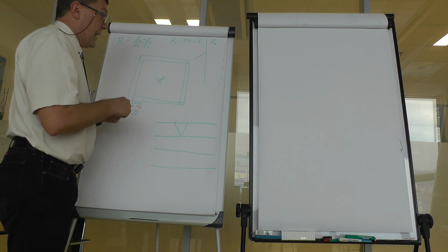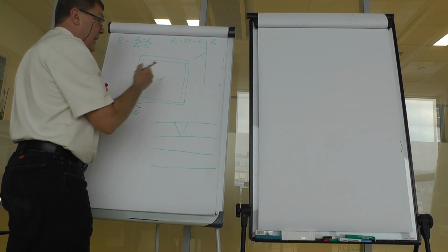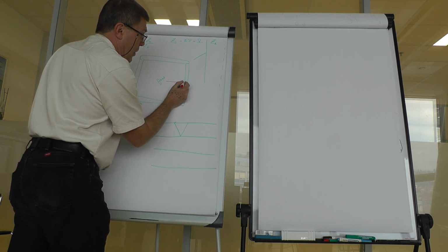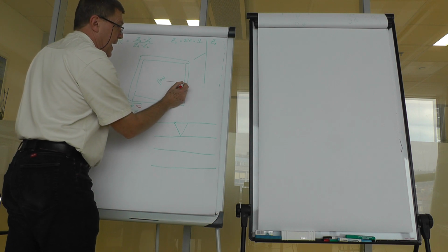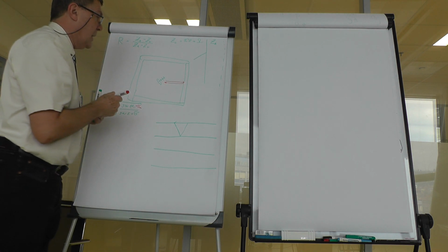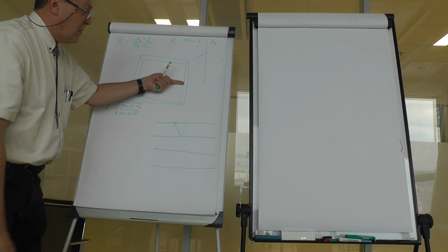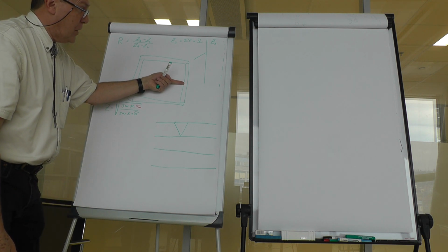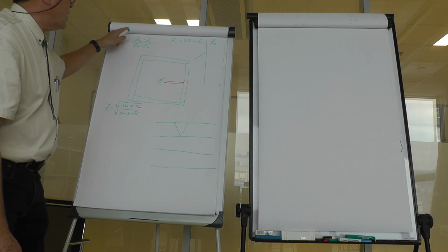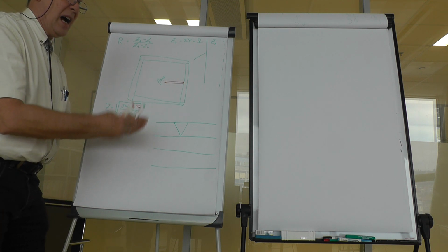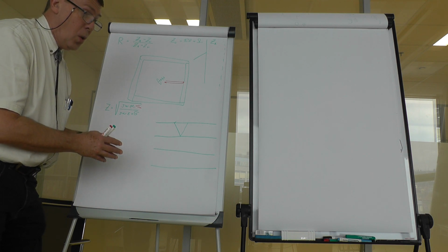The second trick is contained in here, that if you have a wave that goes directly to the boundary and back to the area of interest, to the antenna, then this wave comes under an angle which is close to perpendicular, and the matching structure is designed for that, and there is low reflection.